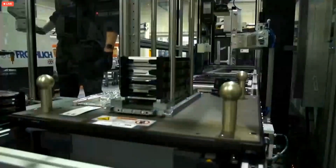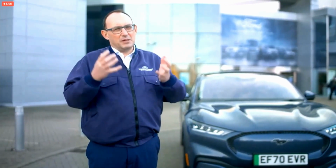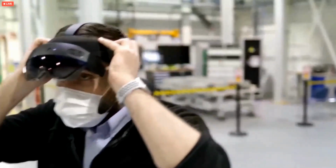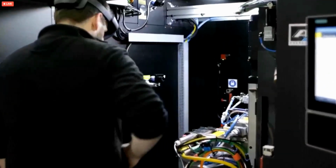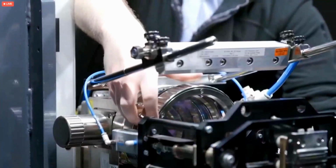So it's important that we have the connectivity that can keep up with that and send that data and store it as quick as we're producing it. We've been able to see data back from the laser process that tells us that we're getting a buildup of heat in our lenses, which means that we need to replace them. We could then contact an expert to discuss it, but we can also use the 5G network in conjunction with a HoloLens system to guide an operator through the process of changing that lens.